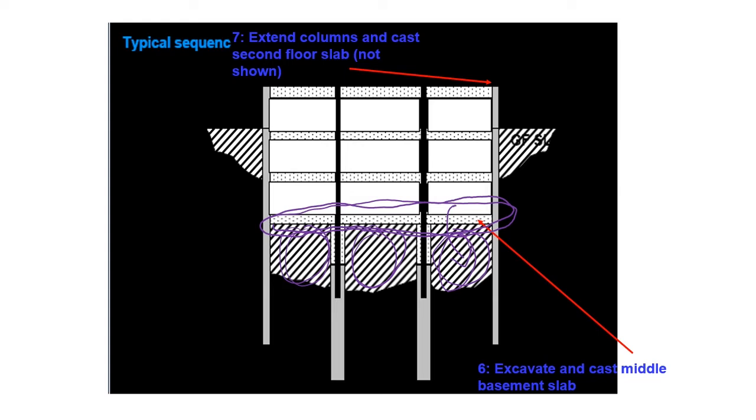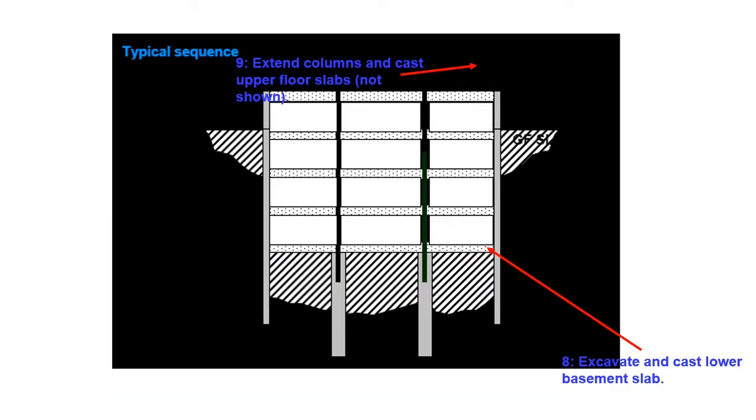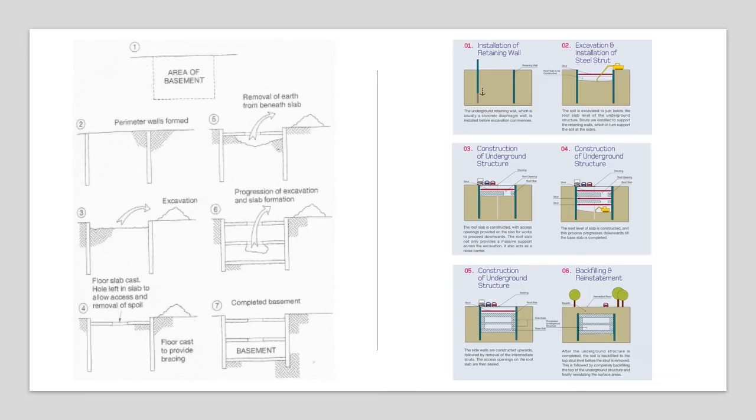And at the same time boleh lagi terus construct column and cast second floor, so makin naik lah bangunan ni and it will repeat again. Kita akan cast lagi here, and maybe if you have another level below, then kita akan excavate lagi tanah dekat area bawah and then bawa keluar, and at the same time bolehlah construct another level. Jadi dia akan berjalan concurrently. Superstructure and underground structure akan berjalan sekali lah. This is the illustration of the top down method.